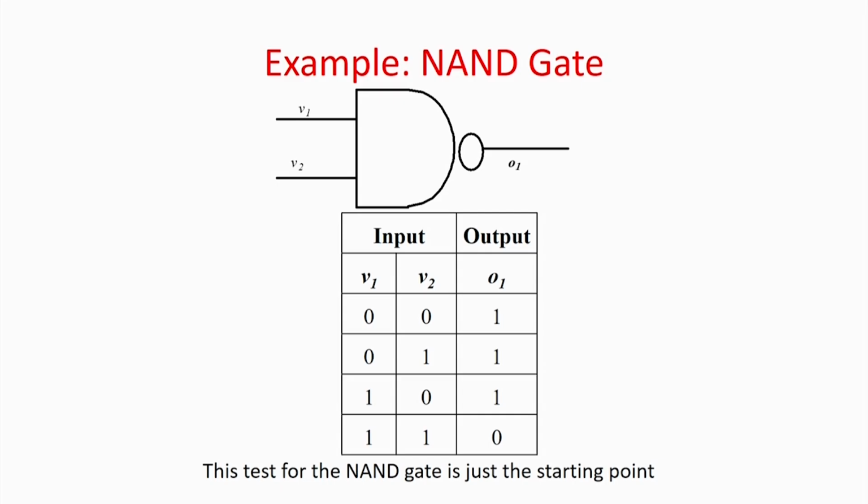So why is it possible? Because we are able to make very complicated systems like NOC and SOC on a single electronic circuit chip. How is it possible? Because we are continuously shrinking the technology from 5 microns to 0.45 or even lower micron technology. Lower micron means that in the fabrication technology, whatever lines and wires you are drawing, the distance between them is shrinking. Once you start shrinking the distances, the problem is that a lot of failures happen.